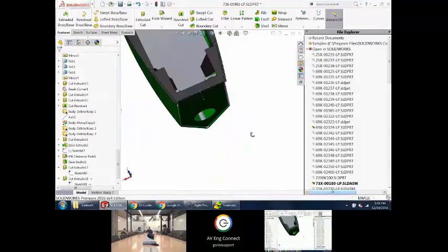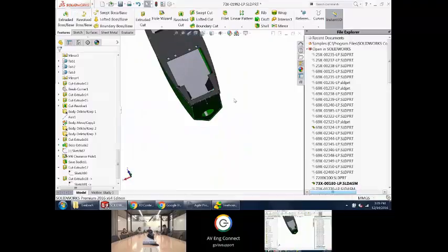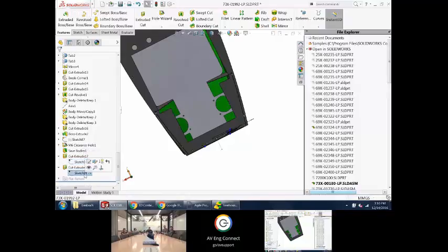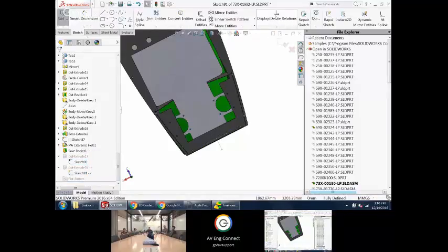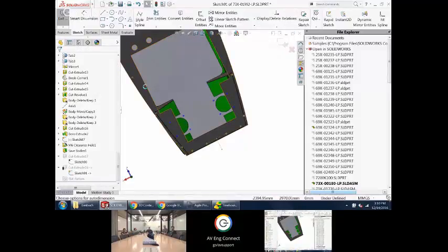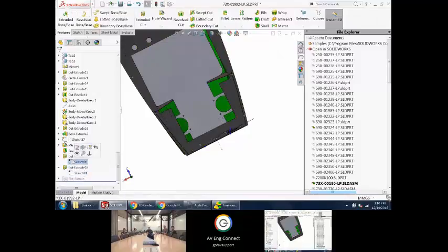It no longer has the magic ability of when the mount changes, the assembly is going to update. That's what an external reference does for you. It gives you that real-time change. This allows you to take an external reference and get rid of it. You see, now this sketch has no recollection of ever having an external reference. So it's pretty easy. You just kill them and then put them back, and it'll just measure off of the model that you've got. And now I have no external references. Hooray!